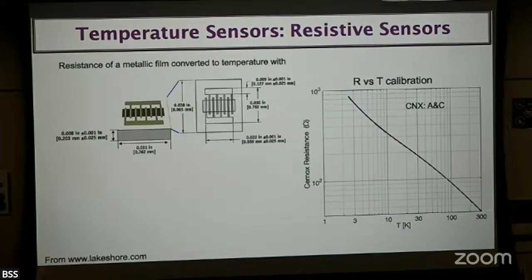When you have this similar temperature dependence, that means, you know, Cernox is just a chip, right? These people deposit on a 6-inch wafer, and then they cut tiny, tiny pieces. So if chips are right next to each other, their qualities are exactly the same. Hence your temperature dependence and field dependence differences are very, very small. So choosing this pair of Cernox is one of my student's greatest jobs, okay?